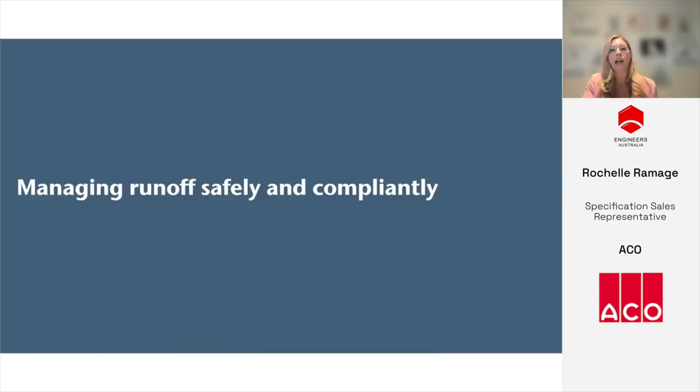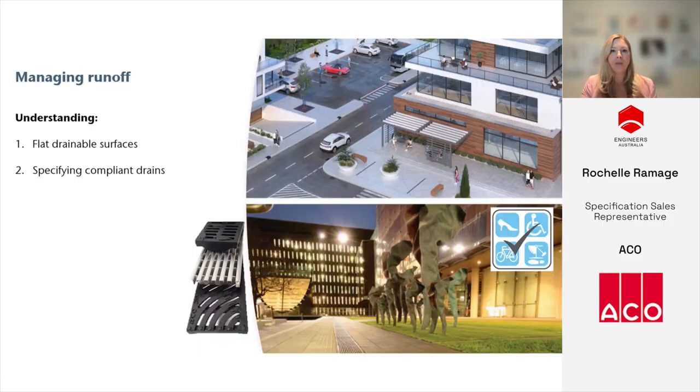We're now going to look at the design principles and legislative requirements of managing runoff. Much of this is designed around ensuring walkability and accessibility. Flat pavements offer better usability, better accessibility, and better outcomes for pedestrians and vehicles. Linear drains support this by collecting water along the surface, rather than relying on complex falls into isolated pits. They interact directly with shoes, wheels, canes, and tyres, so they need to be designed with people in mind.